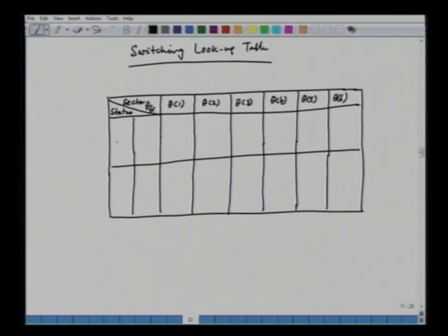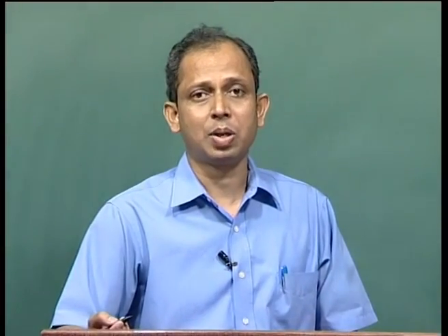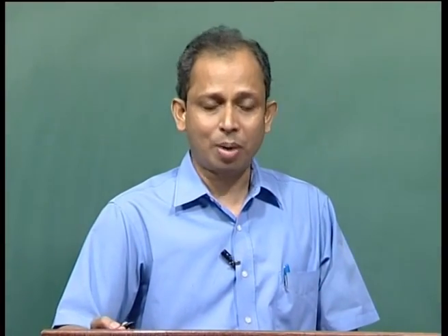So what we have here is this. This is the flux status, d psi is equal to 1. This is the flux status, d psi equal to 0. And similarly, we can have the torque status. As we know, the torque status can be of 3 values. It can be +1, 0, and -1, because we have a 3-level torque comparator.